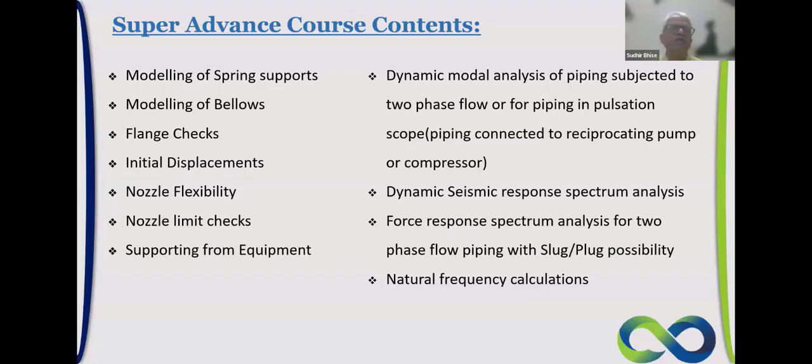Then how to check the nozzle loading limit checks from the equipment, and some dynamic understanding of the analysis, like natural frequency calculation, slug and plug possibility, and two-phase flow. And then piping subjected to dynamic seismic response spectrum method.